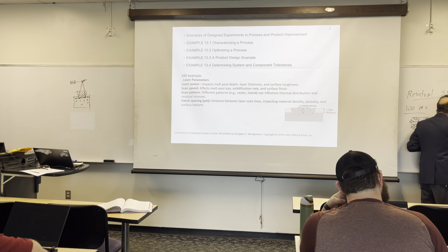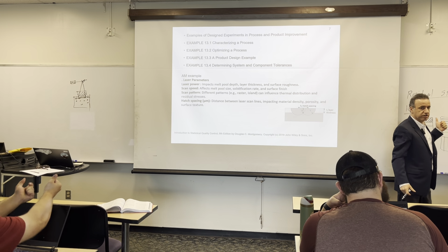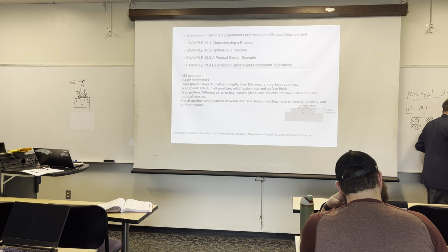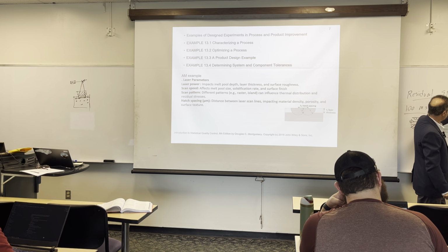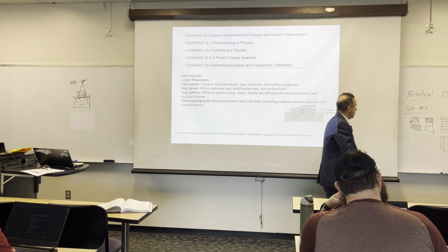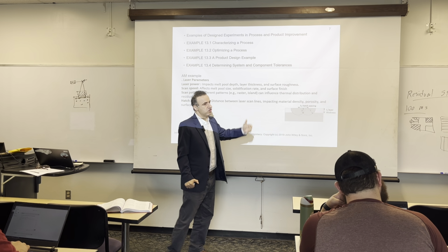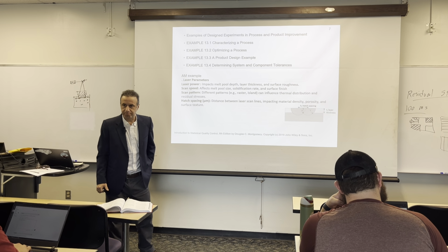And then you have some 100 megapascal from the previous process, this SLM process, and then how much stress can you apply before failing? You got only 200, right? So that is why residual stress is detrimental. That's why we want to optimize the process in a way that we have less residual stress. Okay.